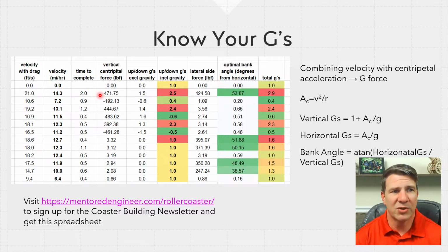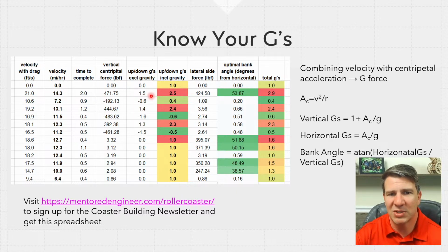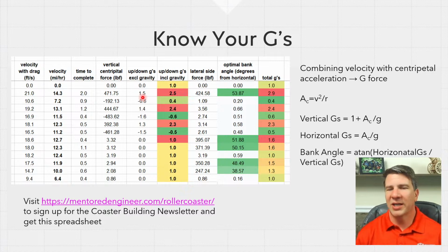And we'll generally measure this in the form of g-forces because I don't care about how much mass I have. I just want to know how many times my weight I'm going to feel. So at the bottom of that hill, theoretically, it's 1.5 Gs from the radius. But since we're on Earth, we're going to have a force directed downward on us all the time. And then anything in that radius is going to add or subtract from that.